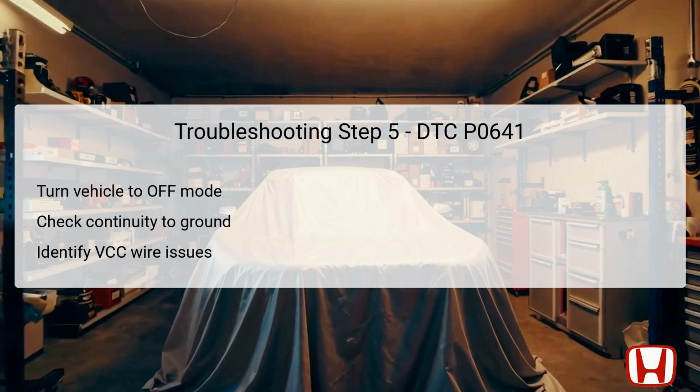If there is no continuity, the wiring might be intact, but further investigation is indicated. In this case, examine any service information regarding the DTCs or symptoms, and if necessary, substitute with a known good PCM to isolate the issue completely.